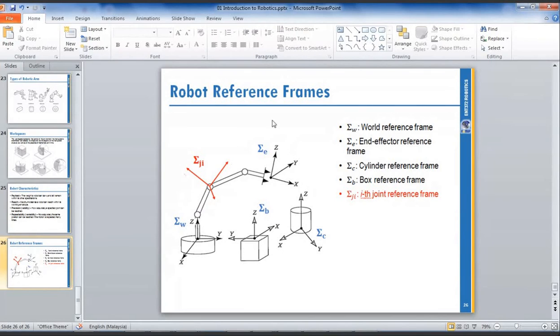So how many degrees? We use the homogeneous transformation matrix to calculate. You see, Y before was horizontal. Now Y is slightly changed, going up. X also changes from this axis to this axis. So how do we find this angle? To find this angle, you need to use the homogeneous transformation matrix or the DH method.